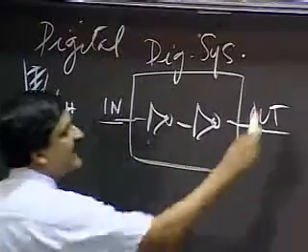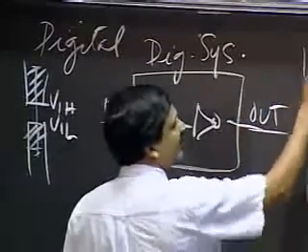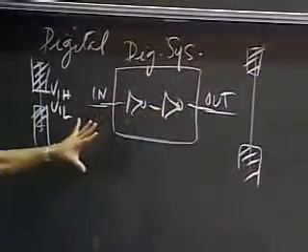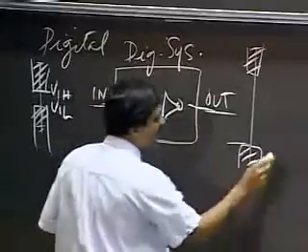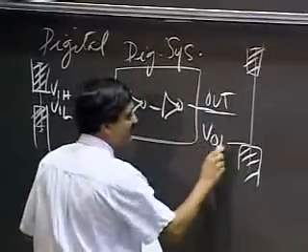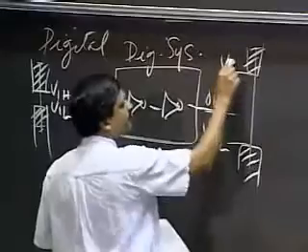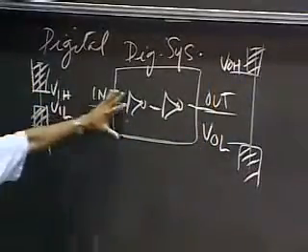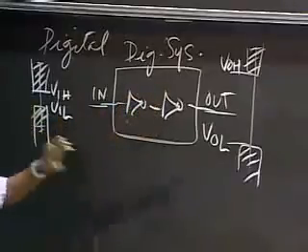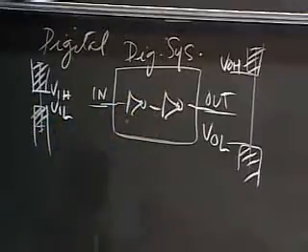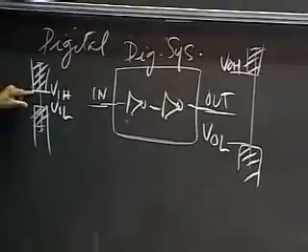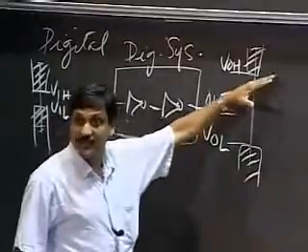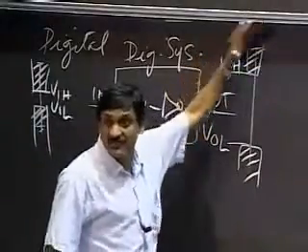On the output, it had a similar set of constraints where we had tougher constraints on devices where we said that the output had to satisfy an output low constraint, output high constraint. What this said is that for this circuit to be called a good digital circuit that satisfied the static discipline, signals that were 1s here should be recognized as such, and if I were producing a 1 as an output, then the signal level should be higher than VOH.